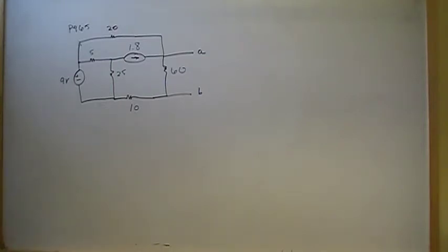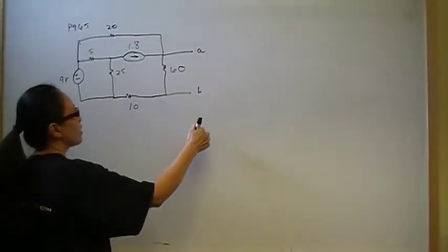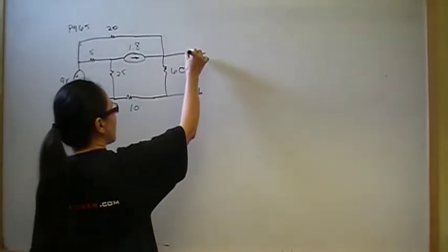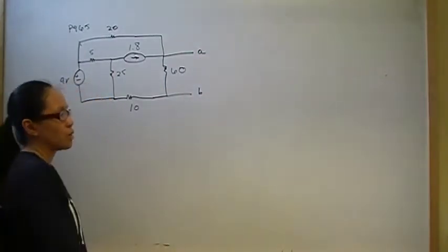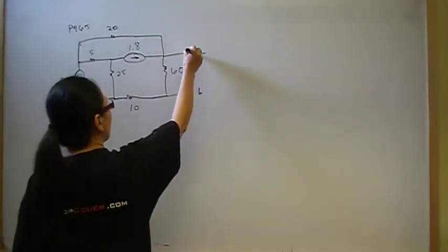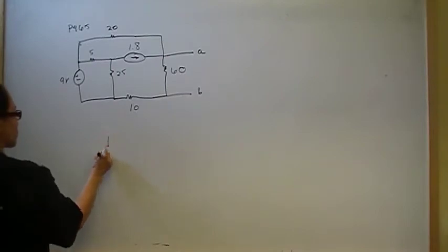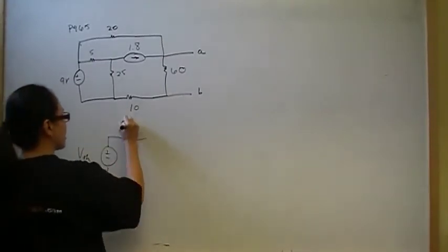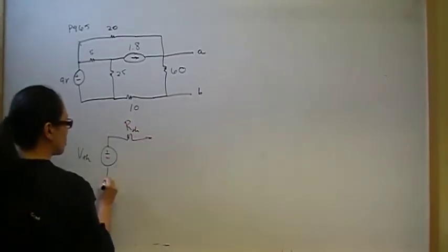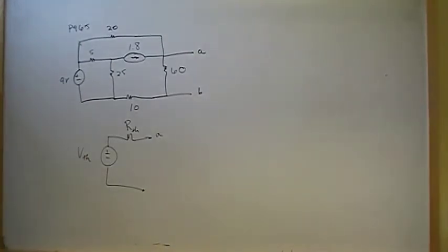A Thevenin equivalent circuit basically says that if you take, like, a wall outlet point of view, you can reduce an entire circuit into one power source, some voltage, and some equivalent resistance. So you can simplify a circuit into a single power source and a single resistance, and that's really cool